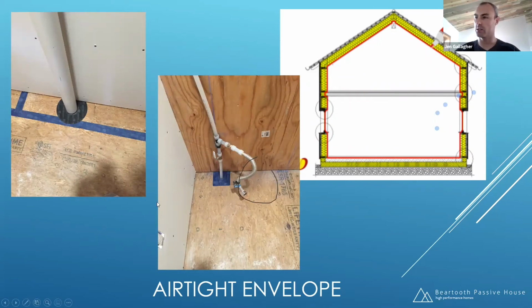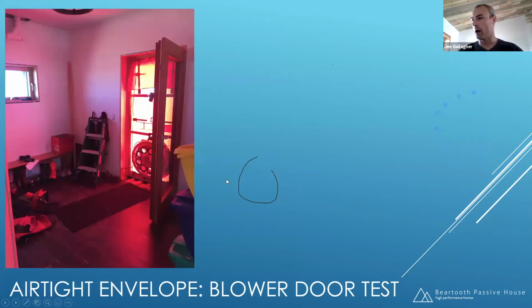The other thing we also have are penetrations. So this is 2 penetrations through the subfloor, you need to make sure that those are sealed. Here we're just using some fancy little gaskets that make it really easy. You could easily tape these pipes, but this is the main water line coming into the house. This is the main drain line, plumbing drain running out of the house. Those are sealed, okay?